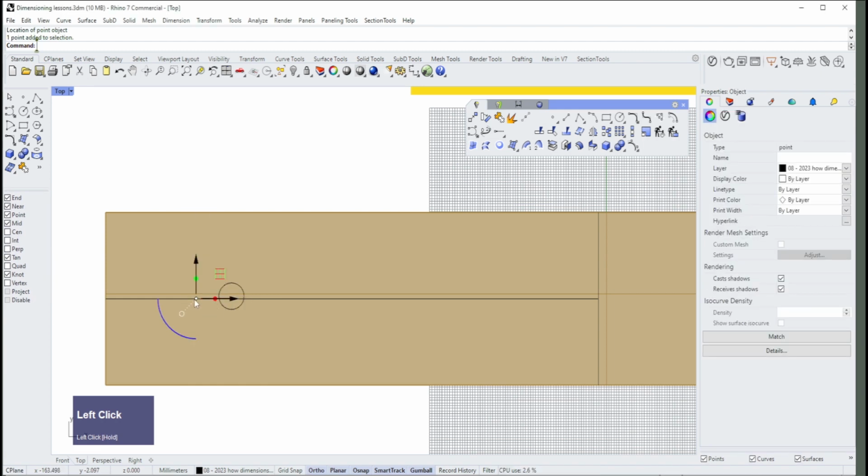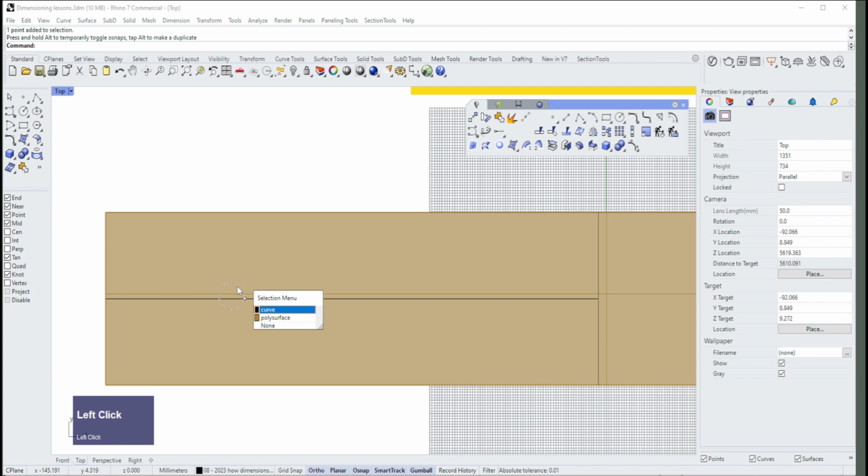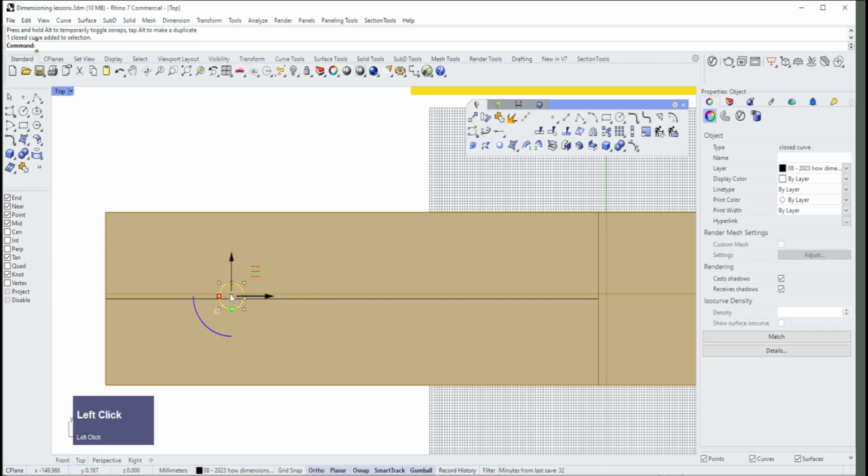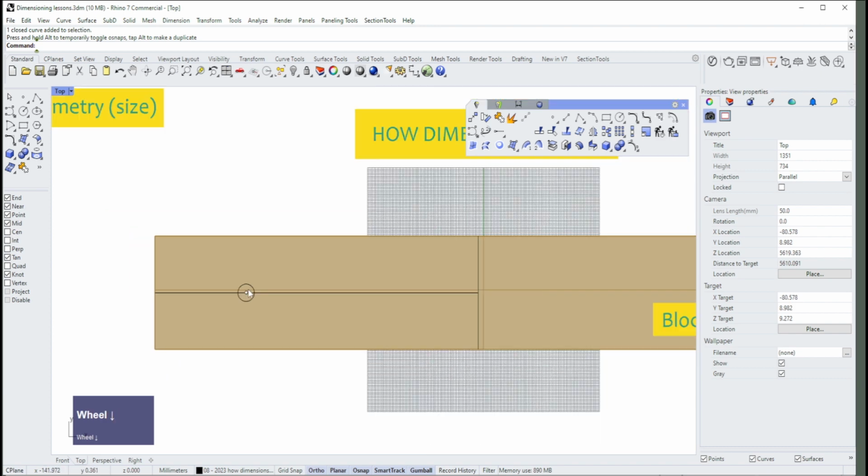I'm going to locate that point at this junction here, just to say that this is like indicating that if you were using a ruler, you would say, well, let's go minus 140 from here, and that would be the point. And then I'd use that point to actually drill a hole, 10 millimeter hole.